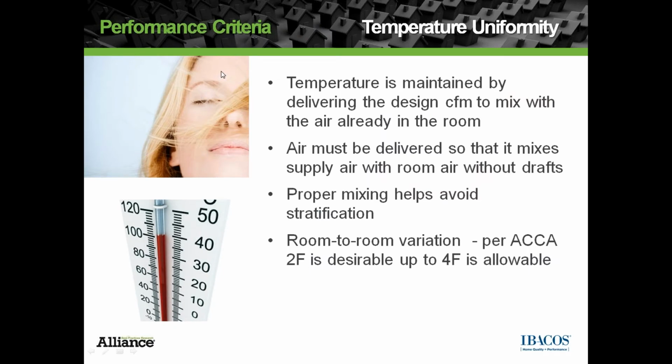Temperature in the room is maintained by delivering that air to the room so that it can mix with the room air that's there, get a nice even temperature. We want to deliver that air in a manner that does not create a draft. A perceived draft is a comfort issue. Proper mixing helps avoid stratification in the room where you have hot spots at the top and cold spots at the bottom.